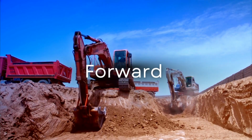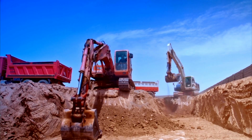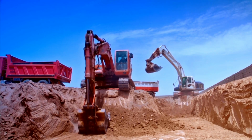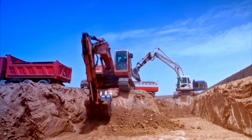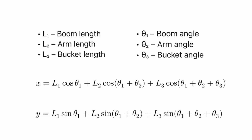One of the most important concepts in excavator motion is forward kinematics. Forward kinematics answers a simple question. If we know the joint angles or cylinder positions, where exactly is the bucket tip? Engineers simplify the excavator into a two-dimensional model and calculate the bucket position using geometry and trigonometry. This allows them to predict reach, digging depth, and dumping height.